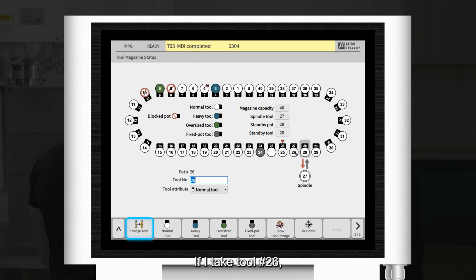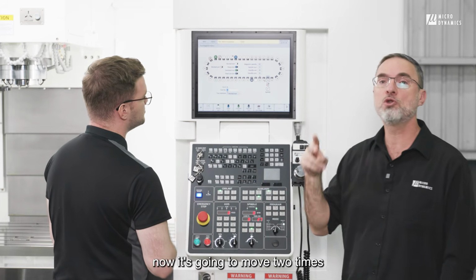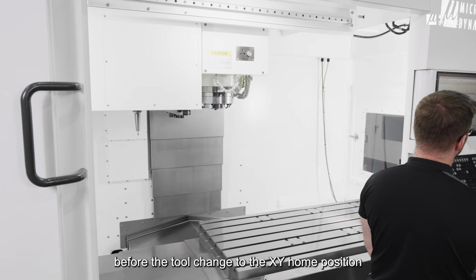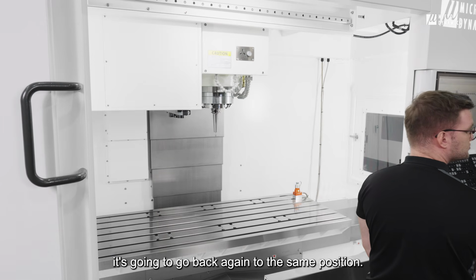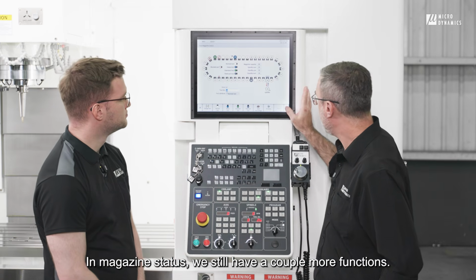If I take tool number 26, tool number 26 now is going to move 2 times. Before the tool change to the XY home position, and after the tool change it is going to go back again to the same position. In magazine status, we still have a couple more functions.